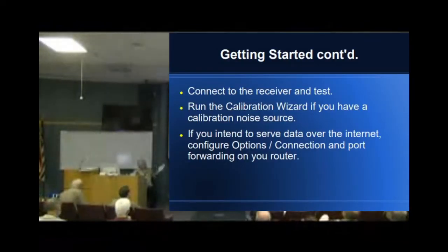When you get your sound card set up and you have everything plugged up, make sure that you're set to like 11025 or 12,000 hertz. That's fully adequate to cover all of the audio bandwidth that you're going to be recording, and it makes it a lot easier on the CPU to handle that.